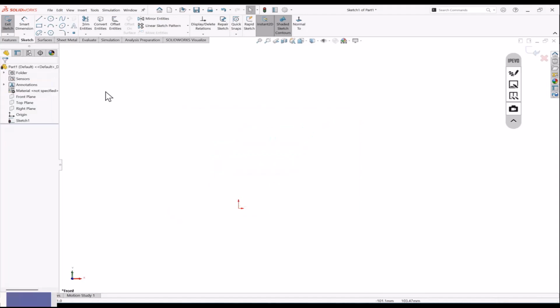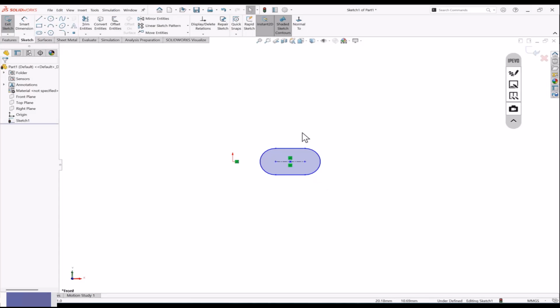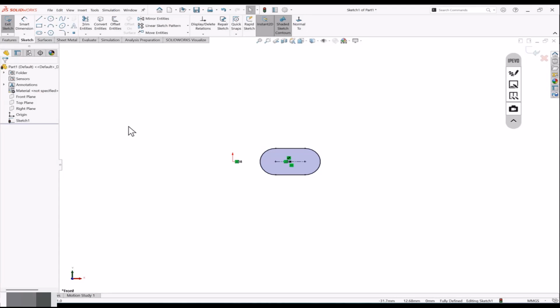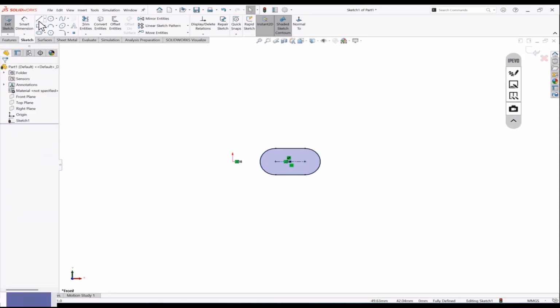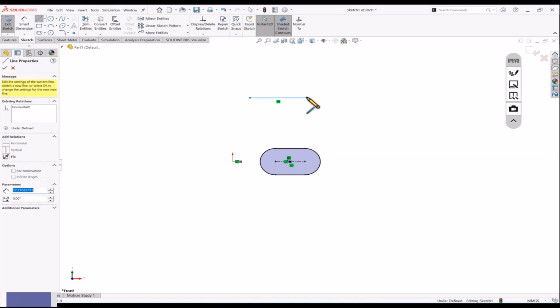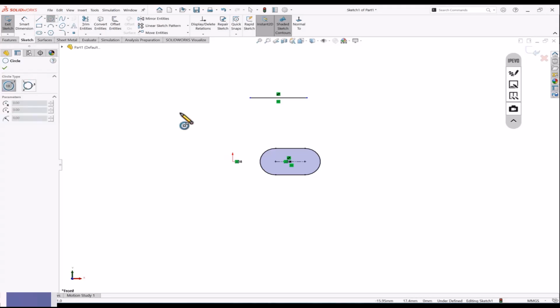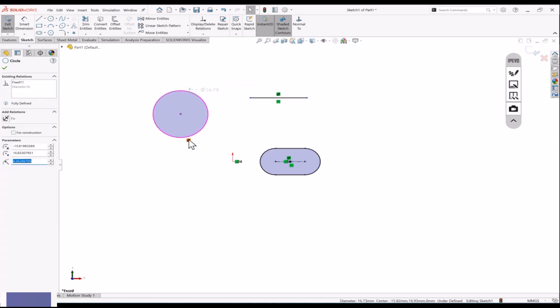Next, if you're making a straight slot, let me make it. You want that slot to be fixed at the position with the size. We'll click on this and take the option called fixed slot. You cannot move it now. And if you want to fix any object you're drawing, you select the object and go to the fix option. Anything, a circle you made, you fix it, so size and all we cannot change. That's one option. You can fix anything.